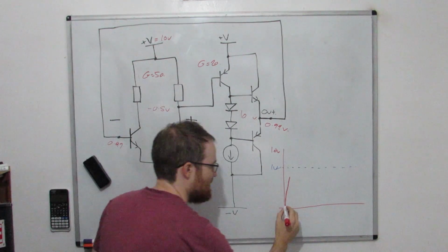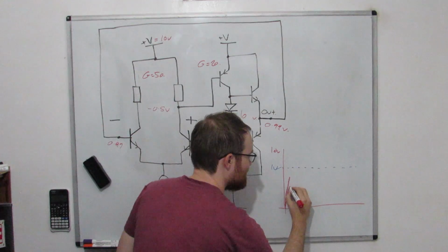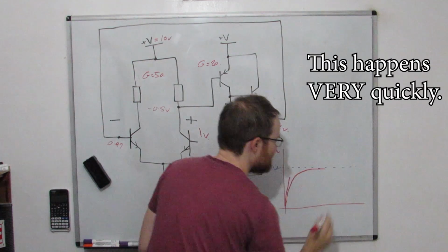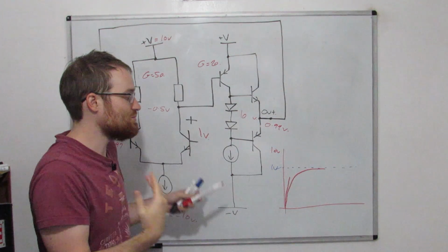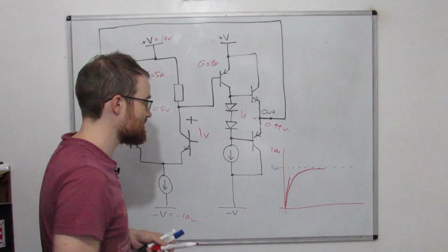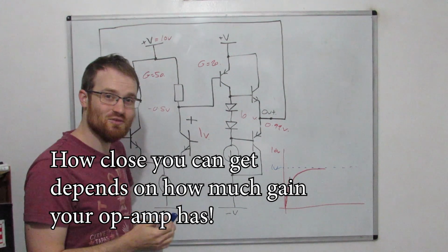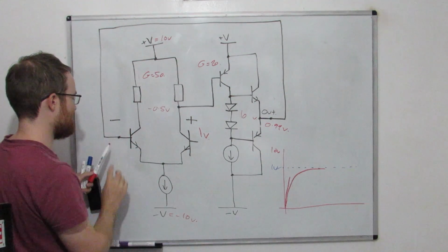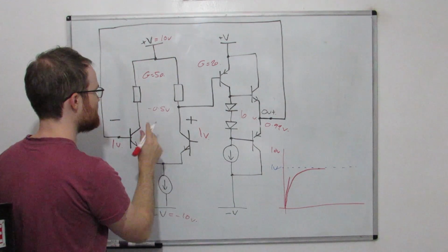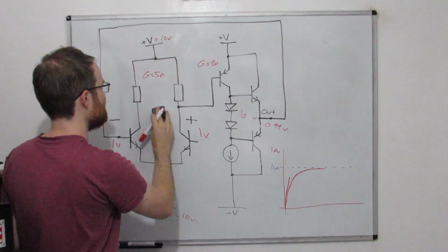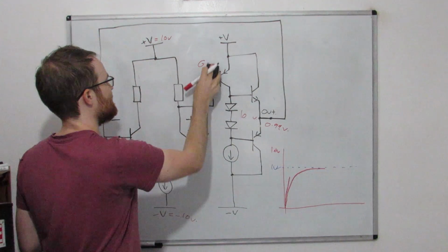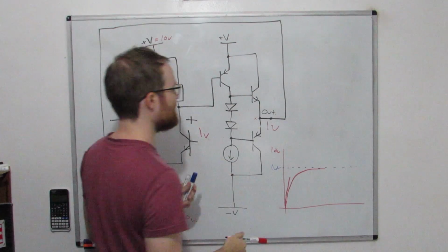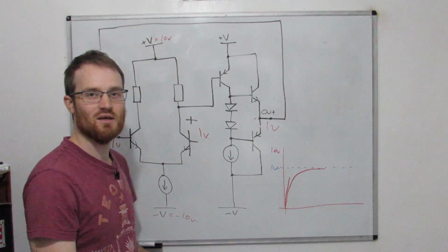We're slowing right down as we approach this, and then eventually we will get approximately equal to 1 volt. Technically you never get exactly to 1 volt, but for all intents and purposes, we'll get to 1 volt, and then there'll be no more difference between the two inputs. So there's nothing left for the differential amplifier to amplify. And so the output has made these two inputs equal.